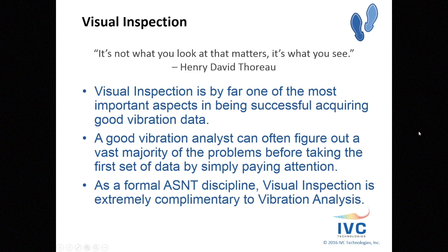Visual inspection, another important step. It's not what you look at that matters, it's what you see. Henry David Thoreau. Visual inspection is by far one of the most important aspects in being successful acquiring good vibration data. A good vibration analyst can often figure out a vast majority of the problems before taking the first set of data by simply paying attention. And I'll estimate that at probably 85% that you'll figure out before you ever have to take data set 1, if you're good. As a formal ASNT discipline, visual inspection is extremely complementary to vibration analysis.